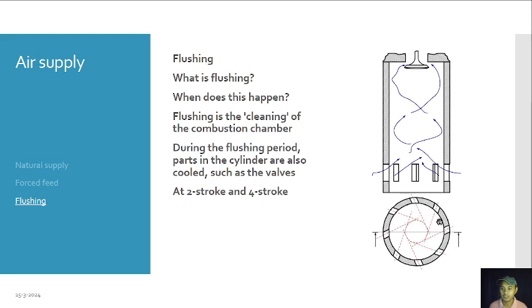The purpose of this is to create a swirl so that there will be efficient entrance of air, and then the air will be distributed all over the combustion chamber, cooling all the parts and removing the unwanted gases.